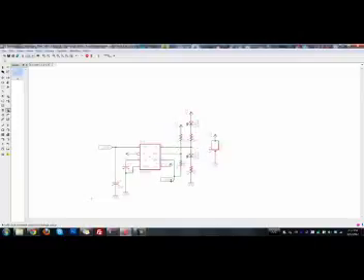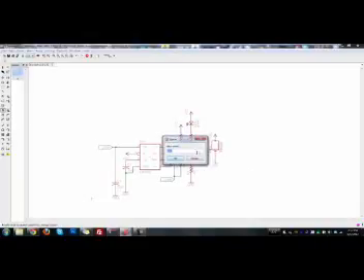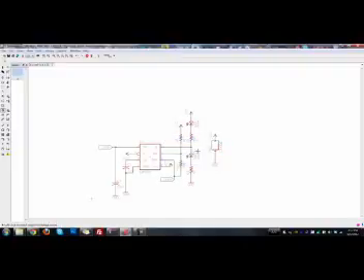And you can also rename parts. So right now this is R1, R2, R3, and R4, etc. But like this one is $1. That's not very nice. So we can rename that. We can just call it BAT if we want for battery. And that's the new part indicator number that will come up on our bill of materials when we generate that.